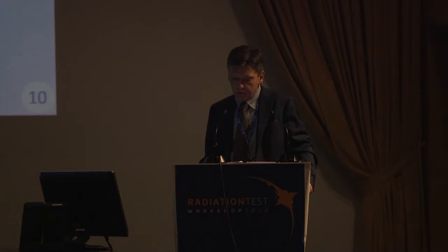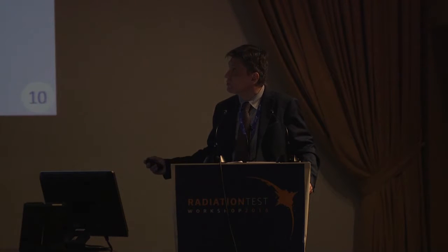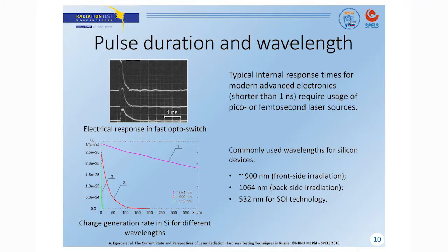For some advanced electronics, the typical response times may be as small as several hundred picoseconds or maybe tens of picoseconds in some rare cases. So laser pulses of the same or shorter durations are needed to simulate effects in these devices. The wavelength is also very important.